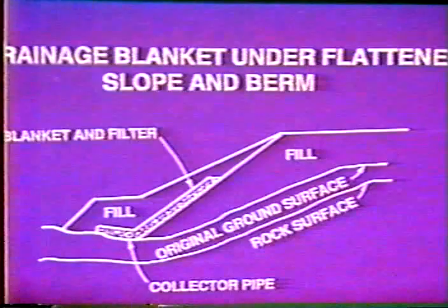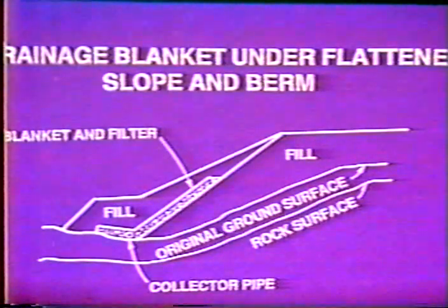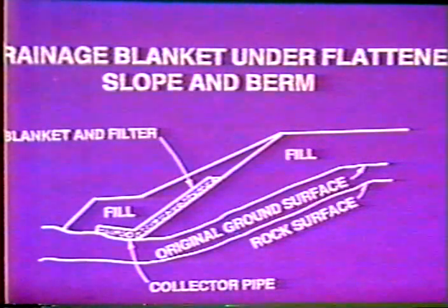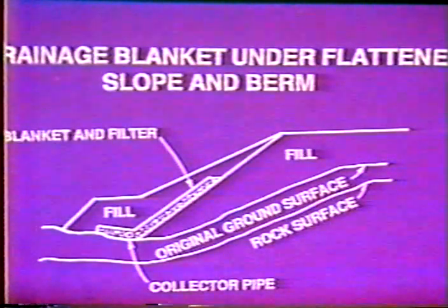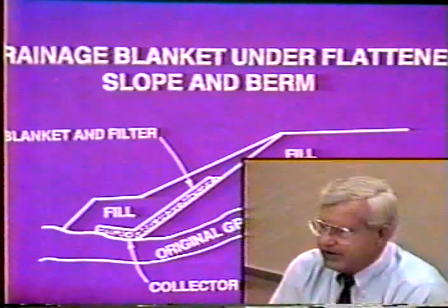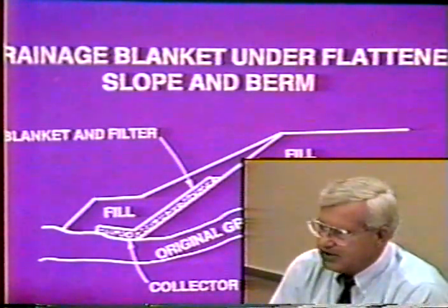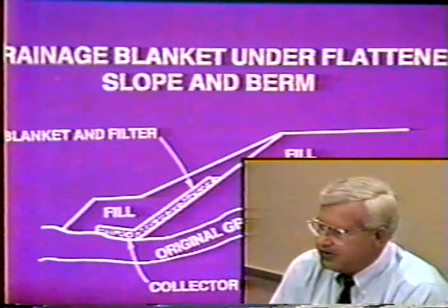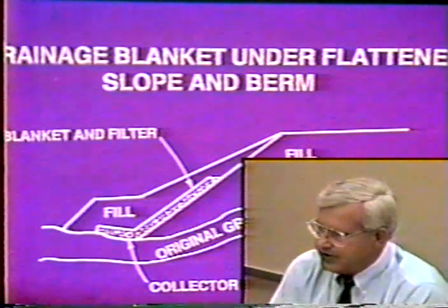If the slope is composed of clays or silts, and also if the fill material is composed of clays or silts, what you want to do is wrap that with a geotextile filter fabric. The reason for that is, if you place the clean stone against the clay or silt, the fine particles from the clay or fill are going to enter the stone and clog it up. Then it defeats the whole purpose of putting it there. What we're trying to do is keep the water table from entering the new flattened slope.